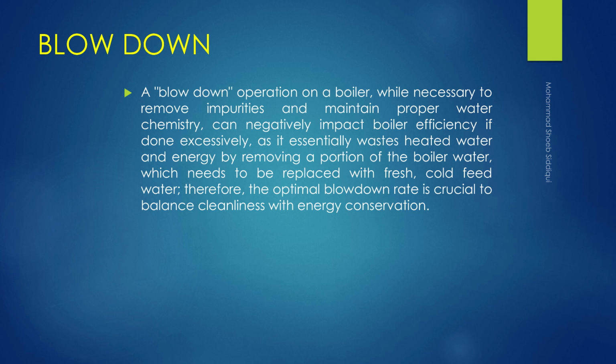Blowdown. A blowdown operation on a boiler, while necessary to remove impurities and maintain proper water chemistry, can negatively impact boiler efficiency if done excessively, as it essentially wastes heated water and energy by removing a portion of the boiler water, which needs to be replaced with fresh, cold feed water. Therefore, the optimal blowdown rate is crucial to balance cleanliness with energy conservation.